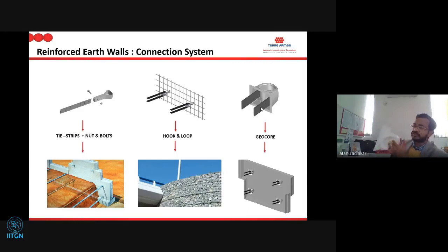And the core, you can see the concrete goes inside. It actually gives you the strength. So there is no steel component. The biggest advantage is, especially when we are building walls in coastal applications, meaning in front of water, there is a lot of apprehension about using this system, but we use it quite extensively because there is no steel, so it performs very well for the long term.